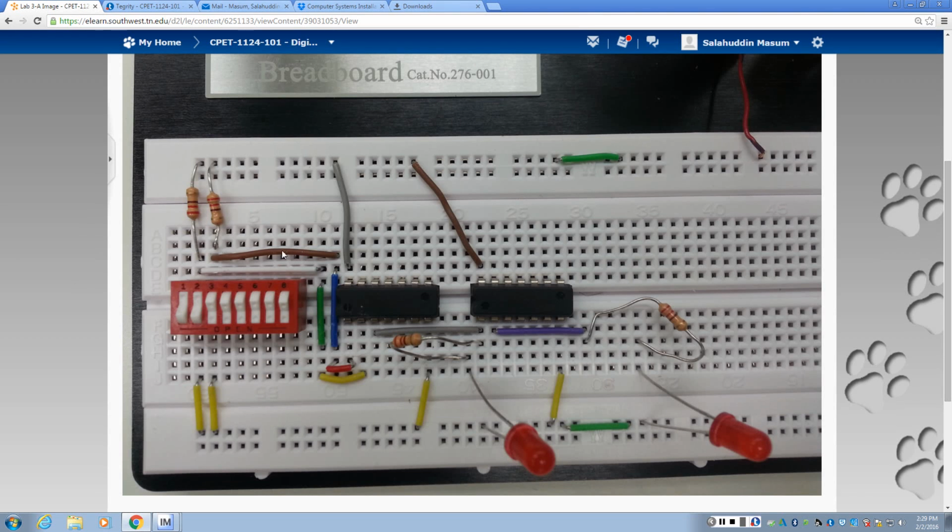Do you see the chocolate wire I'm moving my mouse on? Let's say I connected it here. Instead of this, if I had connected it to these 2 points at the top, it would still be the same thing, the same circuit, because those are the same point. I'm saying all the points on that column are the same point. It doesn't matter if you connect here, or here, or here.